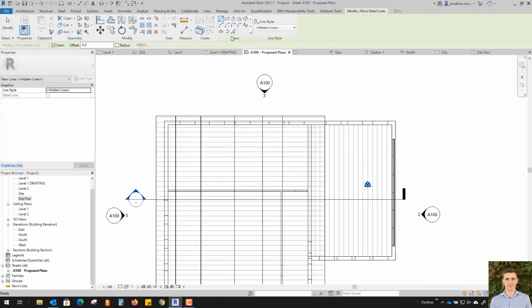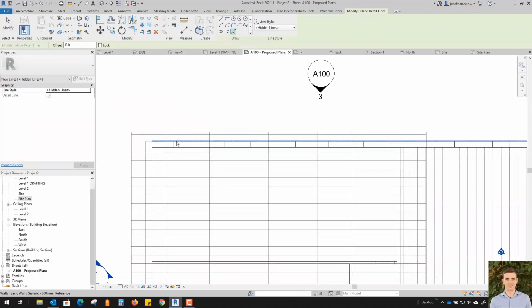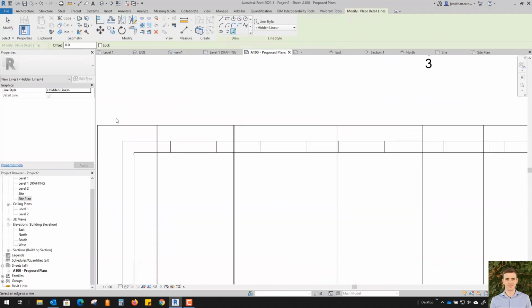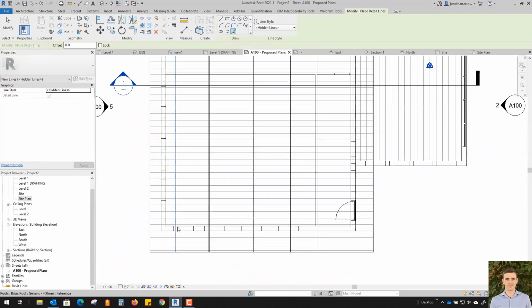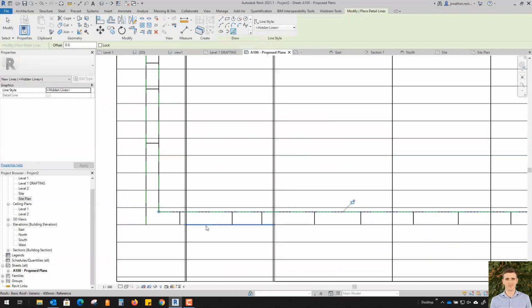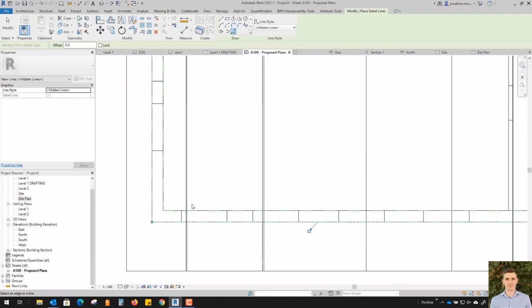In a roof plan view of a building, what I like to do is turn on just the wireframe view for a moment and use the annotation detail line tool. These lines only represent in this particular view, and I select the walls beneath with a hidden line. So this is a dashed line. It's currently showing green. We'll change that to black in a moment.